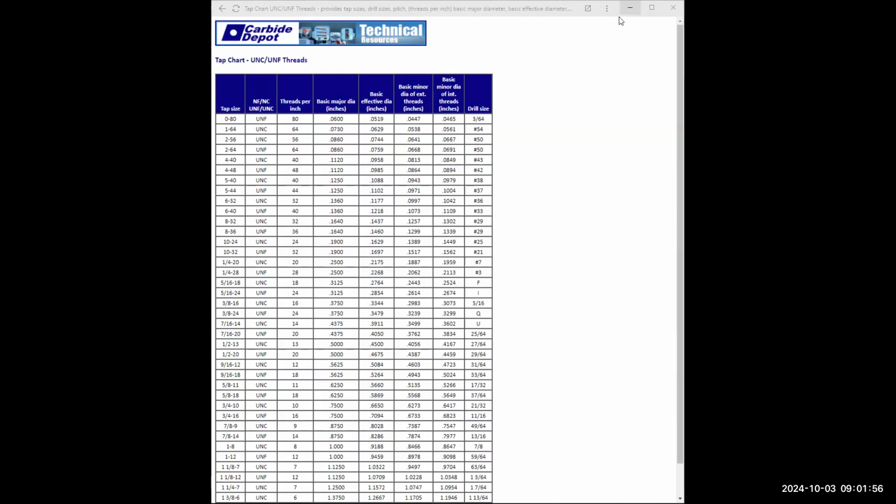Enter. By the way, my trim didn't take right here. Let me try that again. There you go. Enter. Now I'm going to type in E, enter, and erase this line. Enter. Now I'm going to type in change. Again, I'm showing you the hard way of doing this.